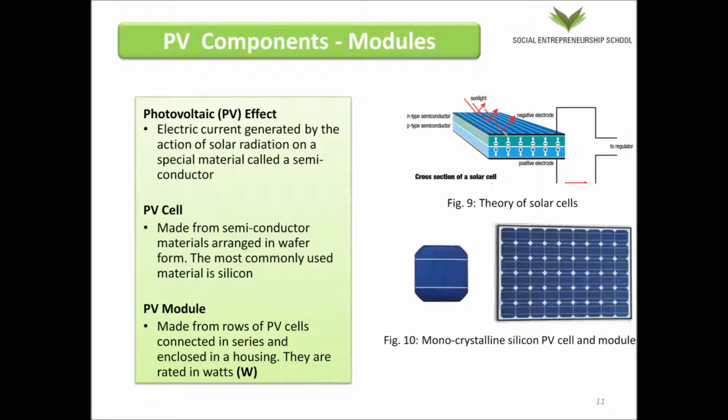Solar panels consist of solar cells, which are semiconductors commonly produced from crystalline silicon. As soon as sunlight or photons hit the surface of the solar cells, electrons are created, and due to the internal electric field of the semiconductor, these electrons can be channeled to the busbars, which are the electrodes attached to the solar cells, and then an electric current can be created and channeled to electric loads to provide, for example, lighting.